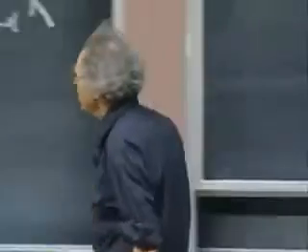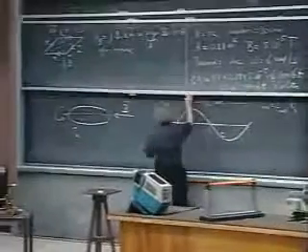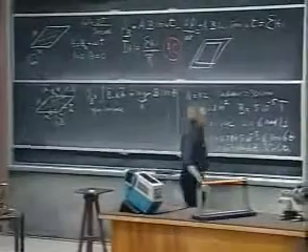You have a permanent magnet, and you rotate conducting loops, windings, in that magnetic field. The higher your magnetic field, the higher the EMF. The faster you rotate, the higher the EMF. The more windings you have, the higher the EMF. And the larger the area of your loops, the higher the EMF. As you can see in the equation that I keep hiding. But that's where it is.